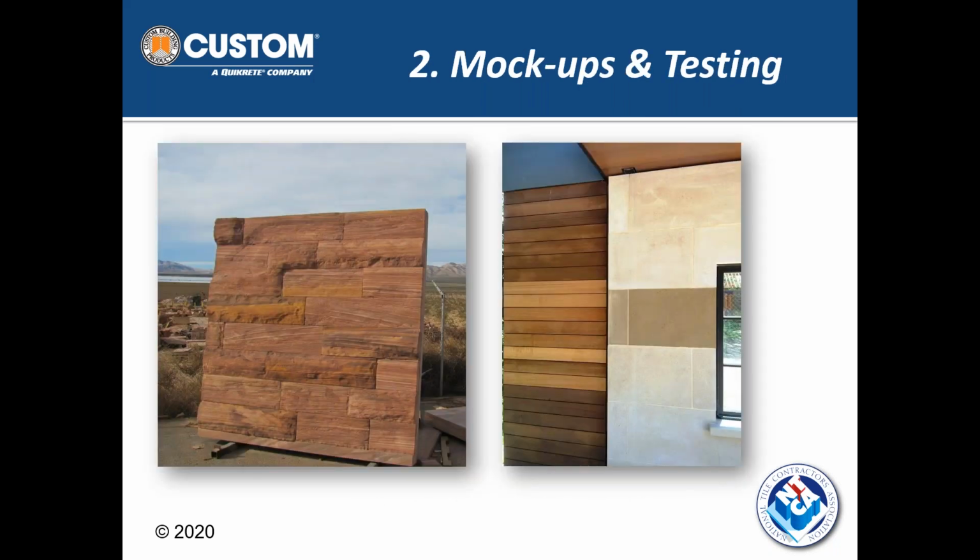So number 2, mock-ups and testing. Again, sounds great. Is it always possible? No. So I'm not sitting here trying to say I live in some euphoric utopia that I don't understand why every job doesn't have a mock-up. But again, if and when possible, especially if you've never used the material before, whether it's tile or stone, if it's in an application you're not familiar with, if you're using different materials associated with it you've never used, and under environmental conditions on the job site. So every job is different to some degree.